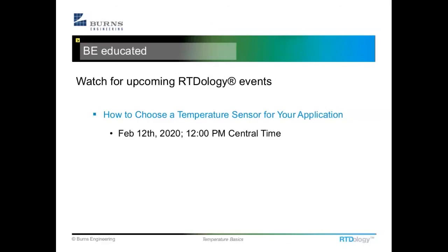And so we track that information, and if it starts to change by, I think it's 3 millikelvin, then we raise a red flag and say that one has gone out of its tolerance band, and it will no longer maintain our published calibration uncertainties, and that goes outside of our accreditation. So we keep track of that to see if there's any kind of trend happening. I think that's what you may be referring to there. I'm not sure how else to answer that right now.